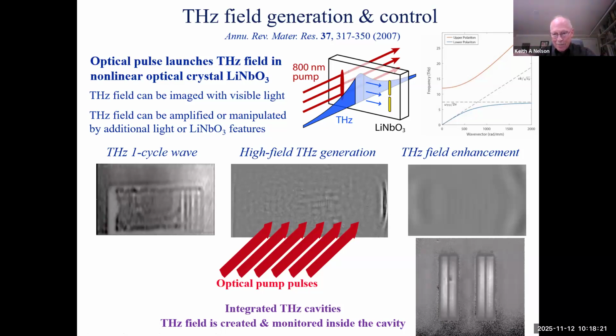In effect, these couple of layers of air and lithium niobate play the role of a multi-layer reflector. An ordinary optical reflector has coatings with many, many layers, but that's because the index contrast isn't nearly as big. When the index contrast is enormous like this, the difference between 5.1 and 1 for the air, just a couple of layers already produce a very high reflecting element.